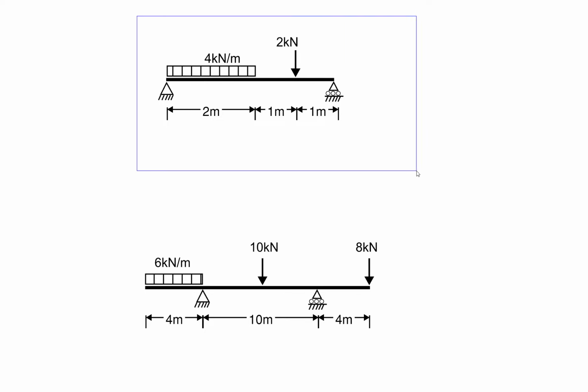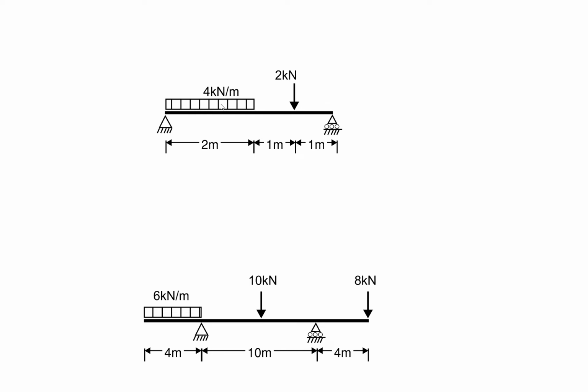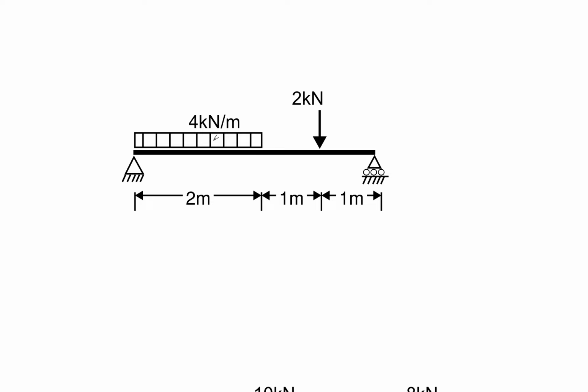The other case, on top right here, from experience, you would need to do equilibrium equations. You can sum up your sigma Fy equals 0 and the moment at one point is 0, and you can work out reactions first, and then based on your reactions you can draw your bending moment diagrams. Let's start from here right now.